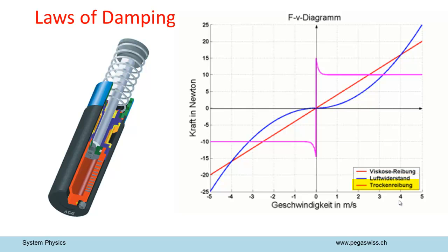The most difficult friction to model is dry friction, which is described in every textbook. The dry friction force depends only on the direction of the velocity, but not on its magnitude. As the velocity approaches zero, dry friction increases slightly. At standstill, static friction, which can take any value up to a given maximum, becomes effective. Thus, dry friction consists of kinetic friction and static friction.